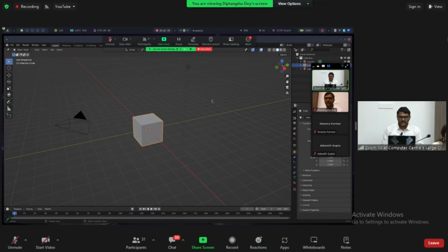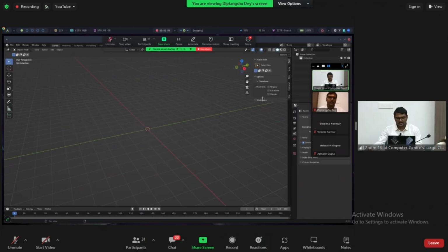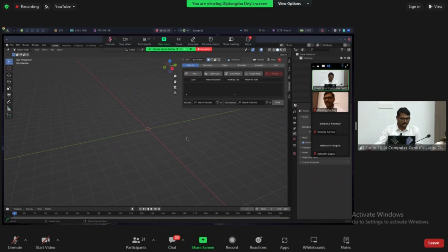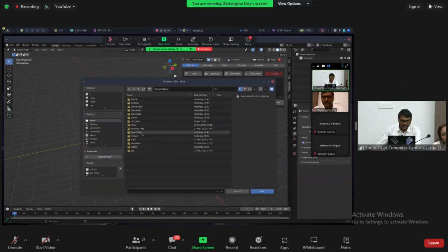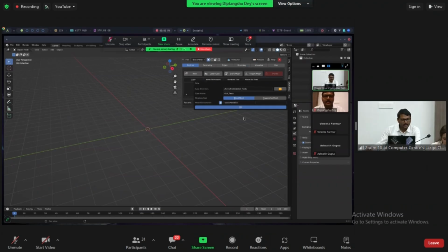So the current state of the add-on is that we can generate blockMeshDict files from it, and I'll be showing a quick demonstration here by making a basic Venturi tube. On my screen you can see the panel for our add-on, which is called Venturial. We can select our case directory. Here I will select a directory called GUI test, and it automatically detects the case name.